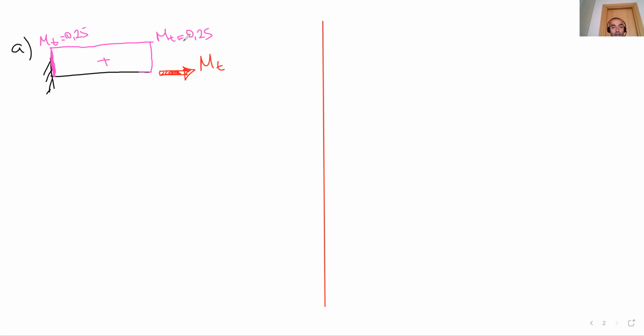Okay, let's do it. Remember, we have to calculate first the polar moment of inertia. How do we do it? Polar moment of inertia is I0 equals pi times R to the 4 over 2. I draw this cantilever as a line here, but it has two portions.